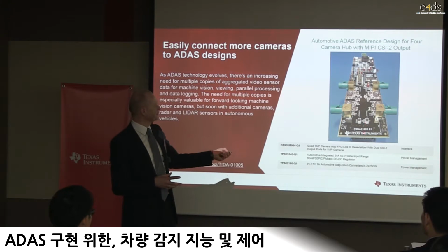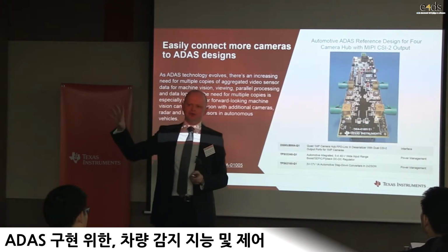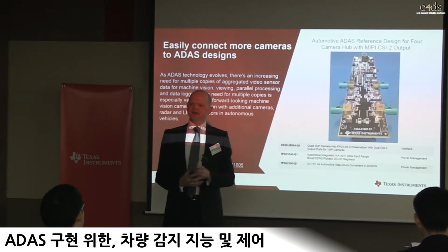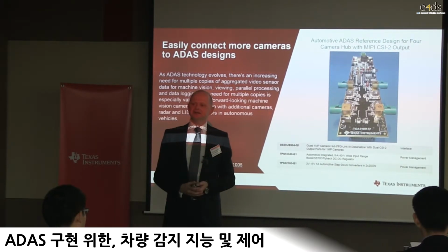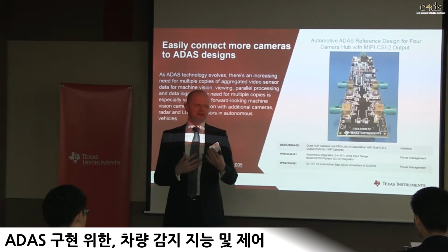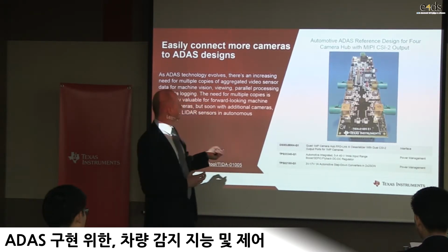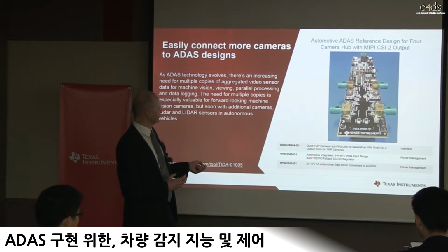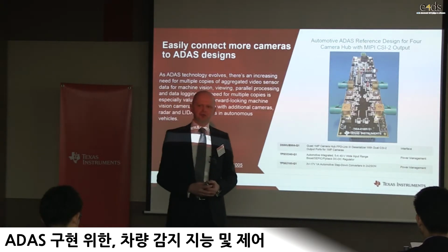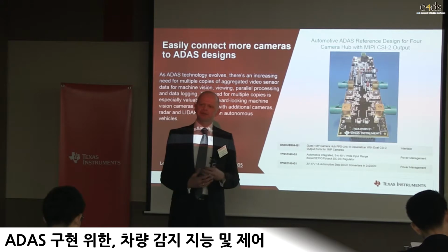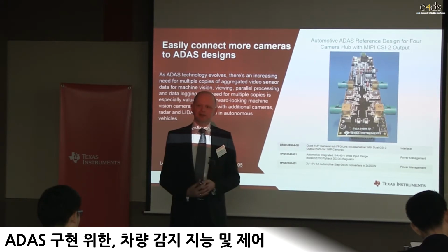This hub design, on the other hand, can be connected to our TDA processor side, where the full system environment can be validated and evaluated. And if you think about it, these are new challenges to the automotive market. We are talking about cameras which have a megapixel plus in terms of resolution, and we are talking here about data speeds which are in the 100 megabit or even into the gigabit per second range, which are new challenges in the automotive domain.